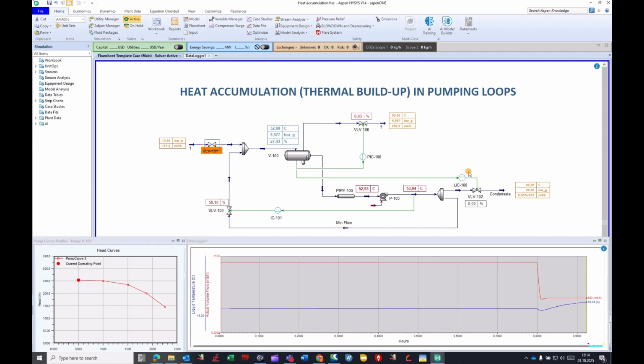In that situation, you can see some transitional behavior for the system, and it can be seen that the level was below the set point. So for a while the valve was closed. Now it's going to open, and it goes through the transition to stabilize. And it seems the liquid inflow is around 50 cubic meter per hour. So it means 450 cubic meter per hour is recirculation, around 90%.